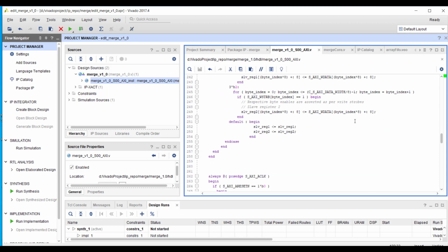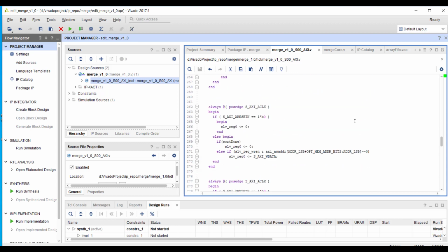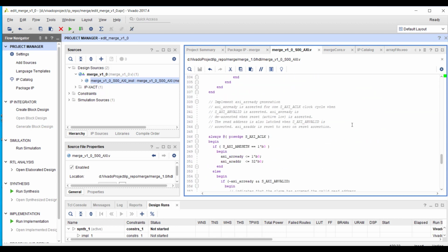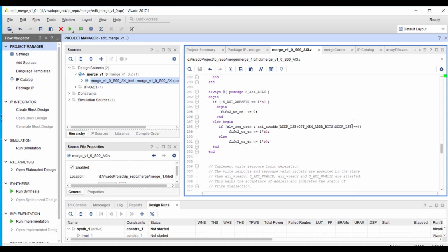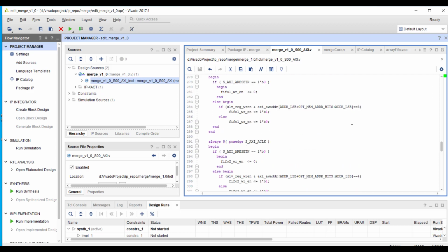And status register, that is the only remaining thing. So remember, the status register, its least significant bit should become 1 when the done signal becomes high from the state machine, and the status register will be cleared by the processor from the software. So usually status is set by hardware, cleared by software, but the control register is usually set by software but cleared by hardware.